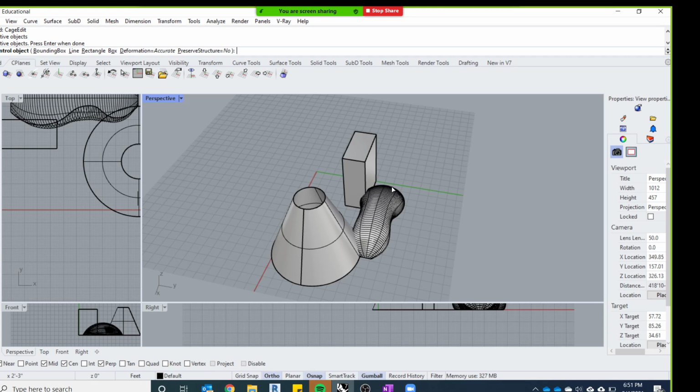And this is how many points you want. Basically what this is going to do, we've kind of gone over control points a little bit. I'm sure you've edited them or used them. When you select an object and you turn on the control points, you can move the control points around on that object. What this does is create a cage of control points that controls all three of these objects simultaneously. So I'm just going to keep it standard for what it comes up with right now.